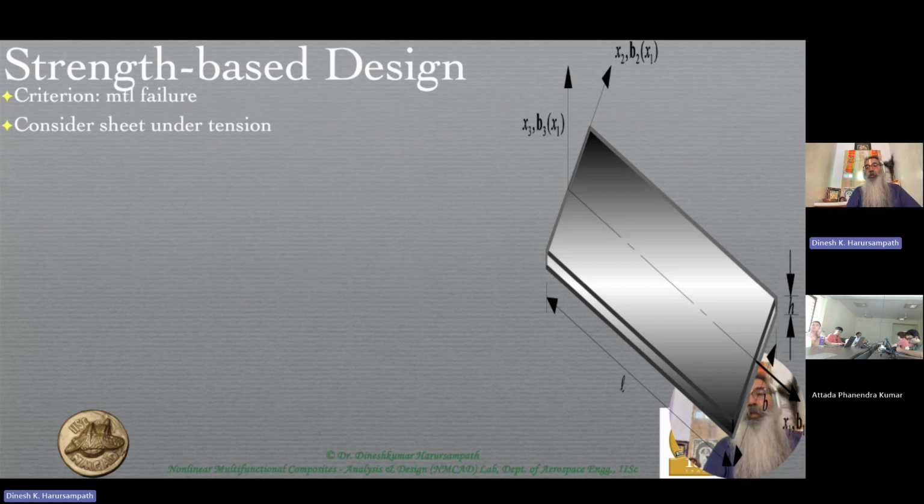Okay, so in this particular geometry that we are seeing over here, it's a special kind of geometry where you can either deal with it as 3D like any other body. You can deal with it as a plate, because h is small compared to the breadth b and the length l. At the same time, b is also small compared to the length, and therefore it can even be treated as a beam, though it's a much stubbier beam than what you typically see, right? So it's purposely chosen this way so that we can introduce multiple kinds of concepts over here.